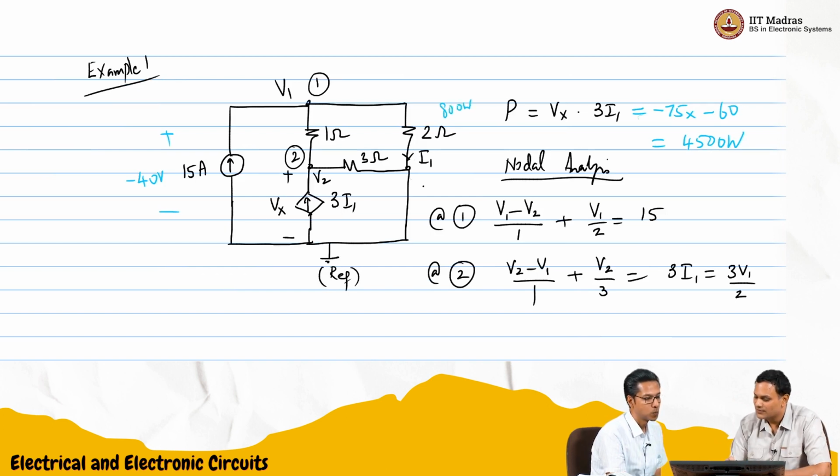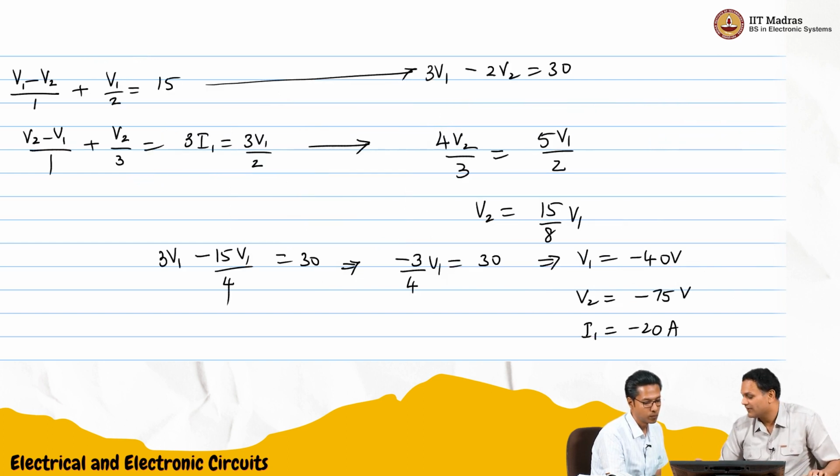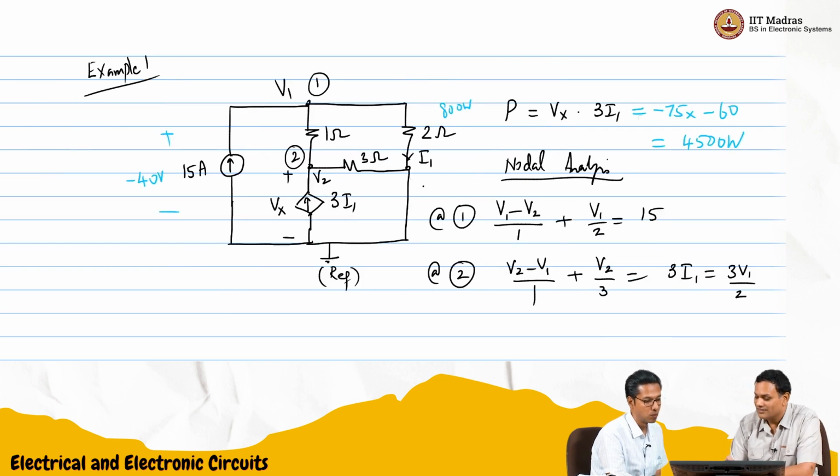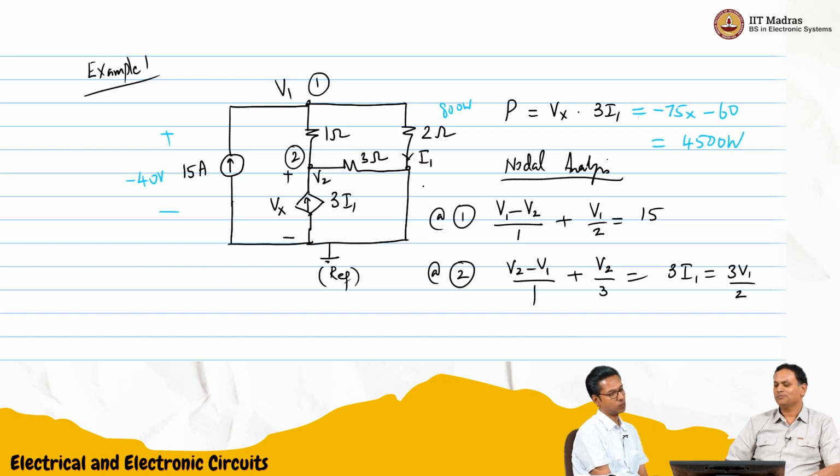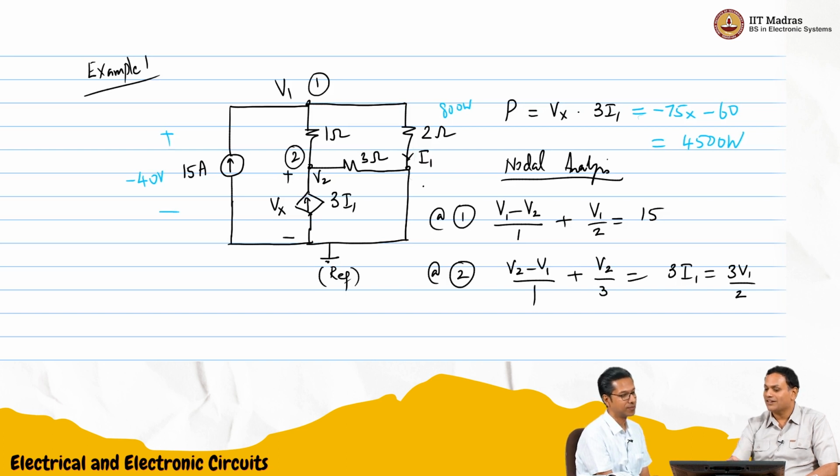And now this one, V1 minus V2, is 35. Plus 35, correct, and it doesn't matter. 35 squared times 1. It should add up. That it will add up, of course. So, very interesting. Because you also need to calculate the current through the 3 ohm and then add I squared R for that as well.